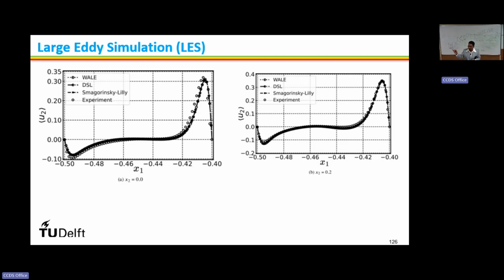I will show how pressure and velocity are coupled. Normally in ANSYS Fluent they recommend using the standard or second order scheme for pressure discretization. Don't use the PRESTO scheme, right? Use SIMPLEC for the pressure-velocity coupling. There are certain criteria, and there is a certain flux limiter. We will see all those things while going through the hands-on LES training session today.